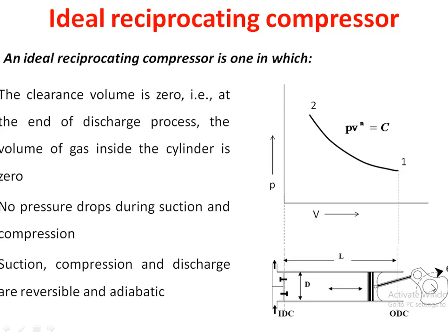As the crankshaft rotates, it pushes the piston inside. Here both the exhaust and the inlet valves are closed. So when both are closed and the piston is moving, the volume available for the gas is reducing as the piston moves inside. When volume reduces, naturally it leads to an increase in pressure. The process of increase in pressure from 1 to 2 can follow different paths. It can be a polytropic process, or an adiabatic process, or an isothermal process, provided there is heat transfer.